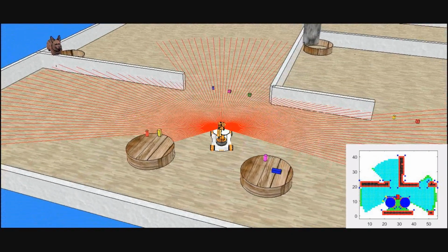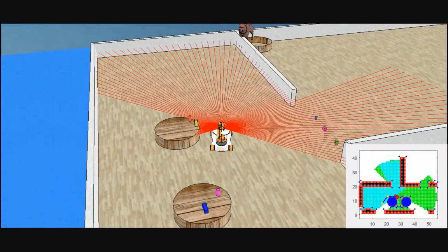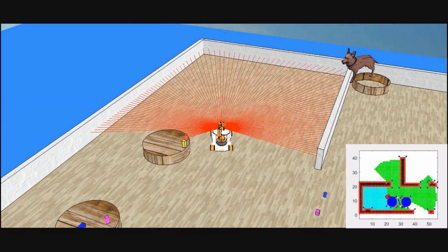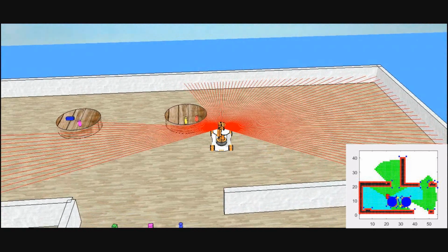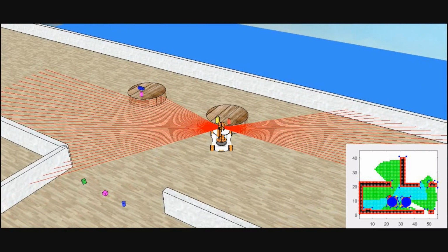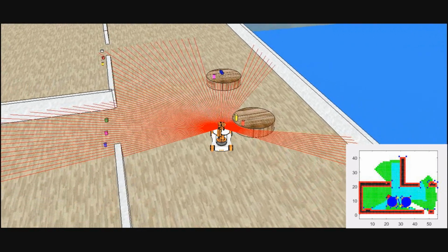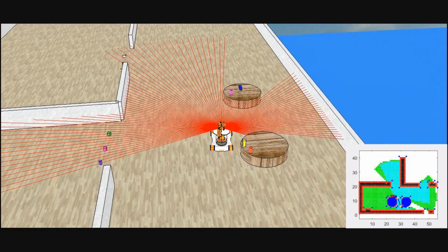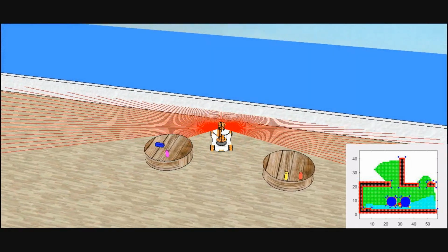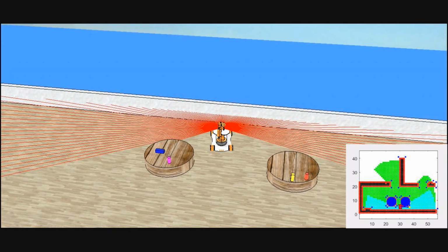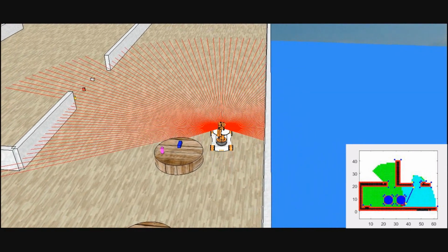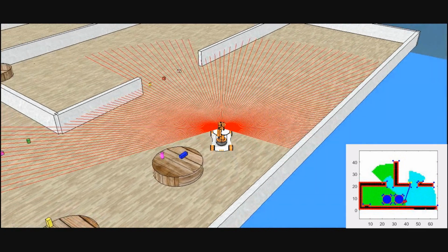Because small objects can fall on the ground and tilt youBot rather harshly if it rolls over them, detected obstacles are discarded when the tilting is too high. We assume that the points from youBot to these obstacles are obstacle-free. These are depicted in green and the current field of view is depicted in cyan. The white points represent the unexplored points. The goal of the exploration is to identify those points as either obstacles or obstacle-free.